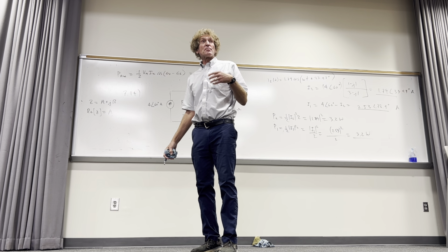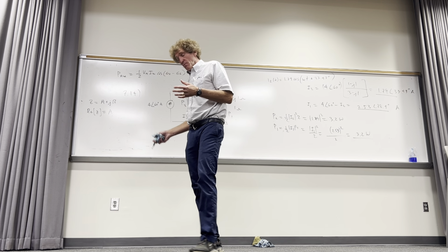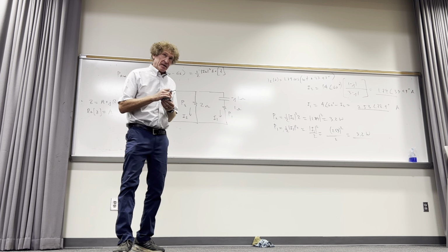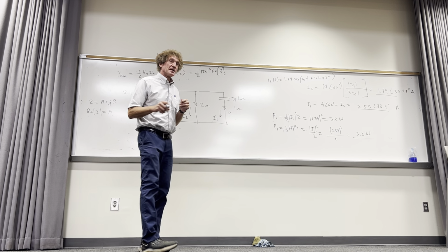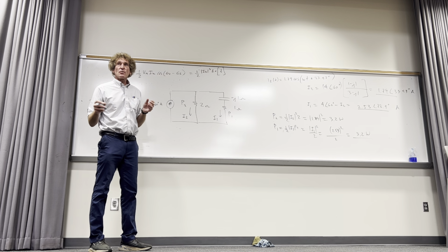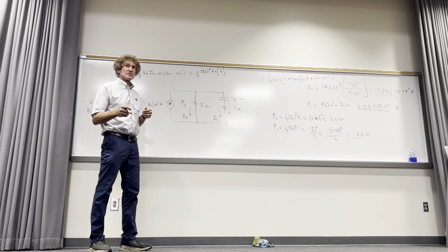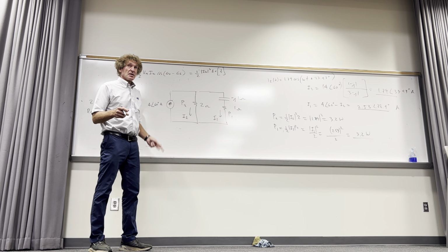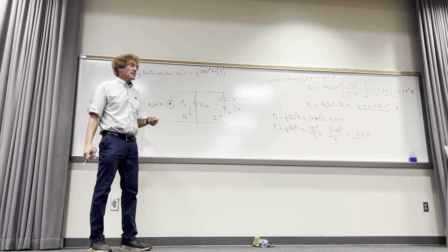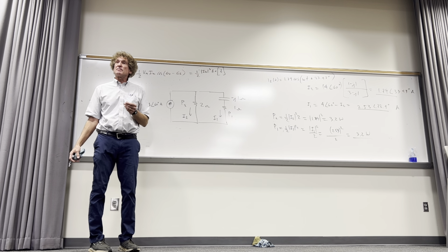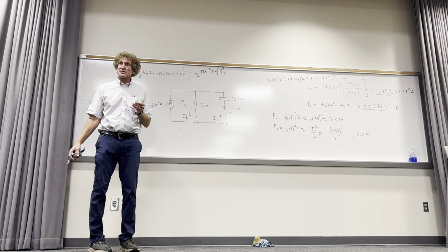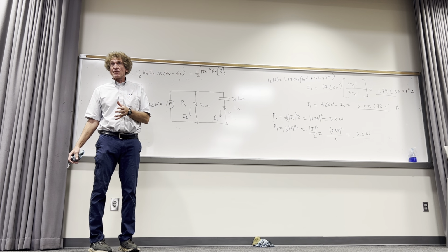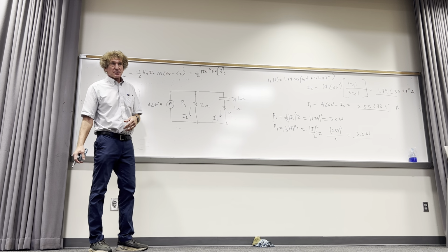We can do another problem if you like, but the one thing I'll tell you that gets people, when they see this, people will hesitate: which way do I solve this? Should I use Thevenin, nodal, mesh? Y'all follow me? If you know your stuff, you'll take a look at this, and current division seems like the easiest, quickest route to get the answers to me. And it should to you too. Do y'all follow me, class? Just remember what I'm telling you. That's why you have to be familiar with the other methods, so you can quickly